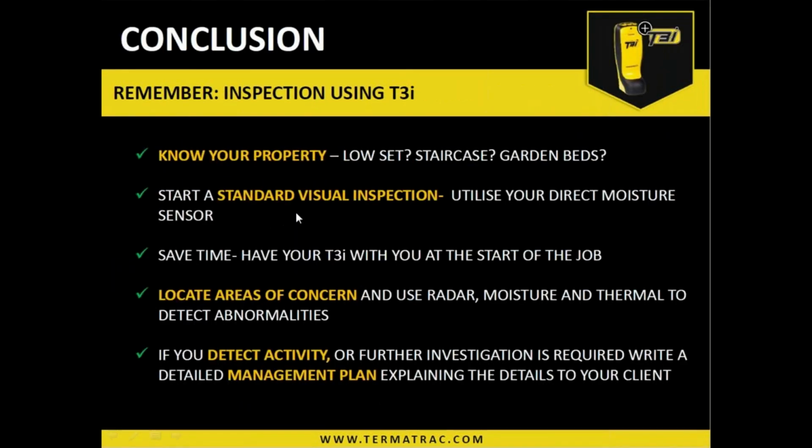All right, so in conclusion, obviously it's understanding our property, the building we are inspecting. So understanding those construction techniques, where termites can travel, where termites can enter and so forth. What is the conduciveness to termites? What on the property or the immediate surrounds can be considered conducive and be an issue for termites? So it's knowing all of that, knowing where to look in those scenarios, and then possibly using the device, whether moisture, thermal or radar in those areas to try and help you with achieving those results.